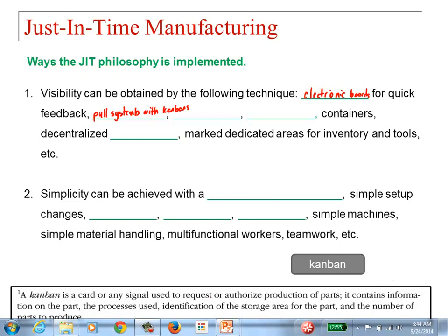What this just-in-time approach does is, instead of having all this material storage in your company and all this final product storage in your warehouse, depending on the requirement from the customer, let's say you place an order, based on that order you're going to start pulling from your system what you need to get that order completed. So as you were seeing, you need one part to produce two parts to produce a component. Then once you produce that, you're going to send a signal to another area of your company saying, okay, I'm using these two parts, I have a space here. Please bring another part so I have at least one of them to produce the next one.